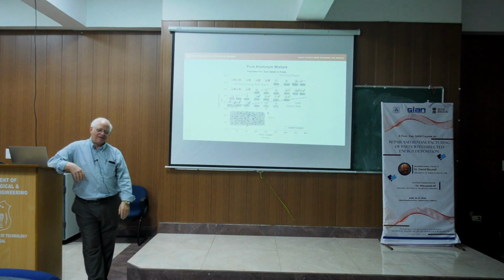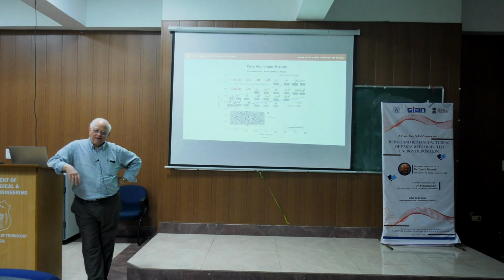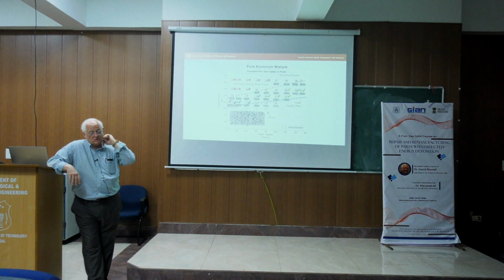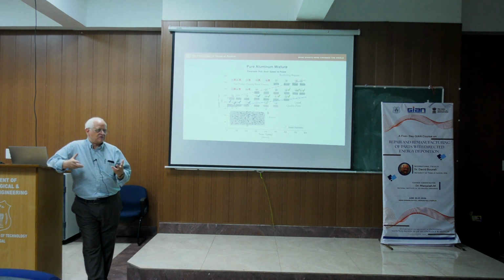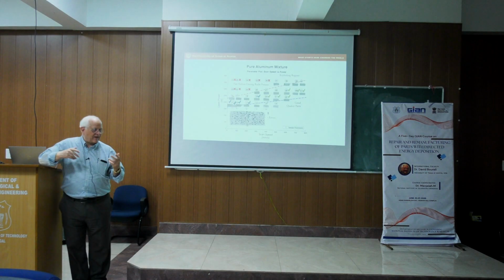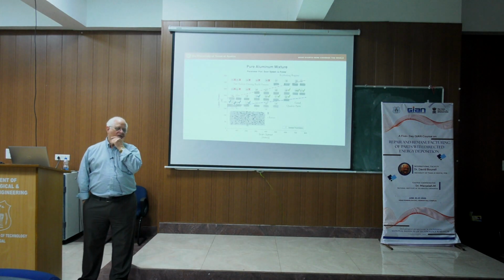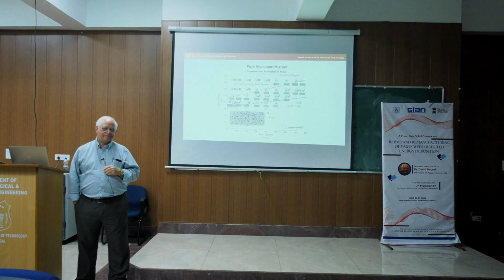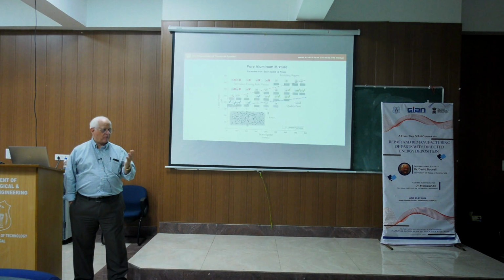This is, I think, part of the motivation for adding rare earths like scandium to additively manufactured parts. They do it because it increases nucleation sites, so you can deal with the rates that way. But other than that, for greater anisotropy, I think that's really about the best you can do.